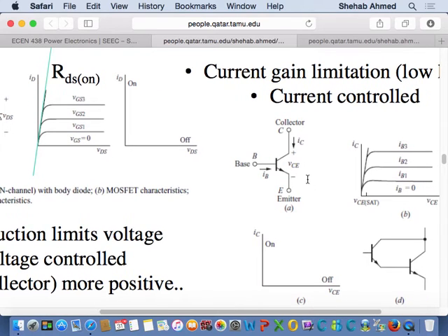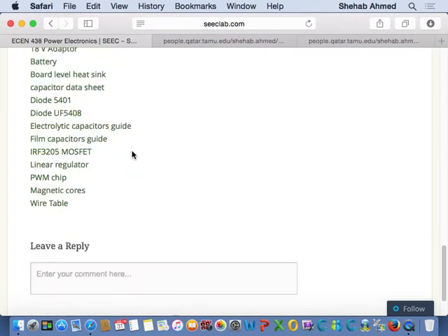How about in the BJT device? What is the voltage drop across it equal to? Yeah, it's VCE, and you were always considering that to be 0.7 volts, right? In your 325 courses, you're already considering that as 0.7 volts. And that's typically the same voltage drop that you considered for the forward drop of the diode, right? You were using that as well. So in low power circuits, typically, yes, 0.7 volts is acceptable to use. But for example, in power electronics, it would be different.